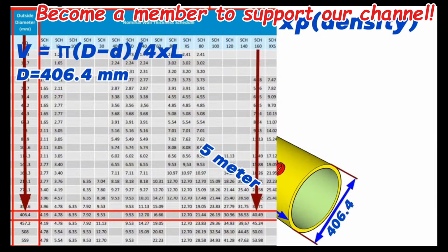So, we found that the inside diameter of the 16-inch Schedule 160 pipe in our example will be 325 millimeters. These dimensions should be converted to meters also. Then, the outside diameter of the 16-inch pipe in our example is 0.406 meters and the inside diameter is 0.325 meters. We also know that the length of the pipe is 5 meters.